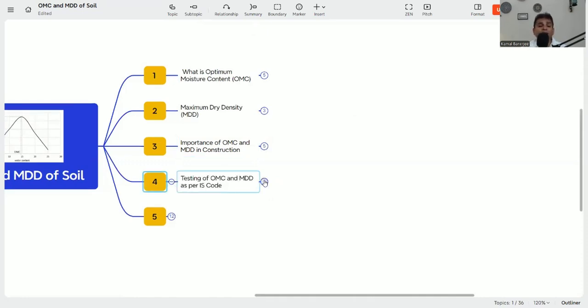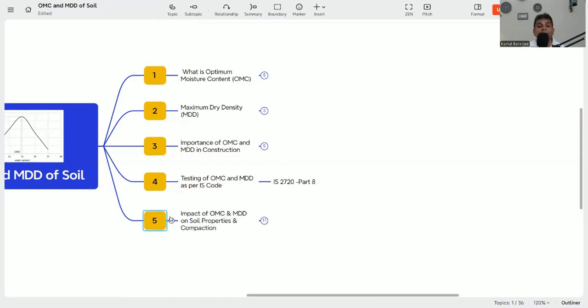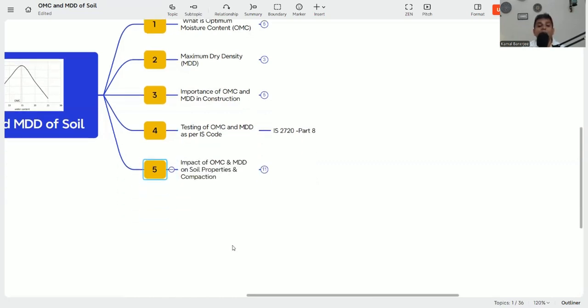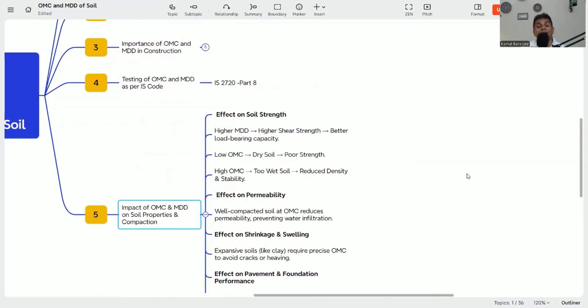And testing of OMC and MDD as per IS, that is IS 2720 Part 8, I already discussed. But how to do the test of OMC and MDD is a separate subject, and in another video I will discuss how you can perform OMC and MDD at site. The next part is the impact of OMC and MDD on soil property and compaction. Why? Because in soil engineering or geotechnical engineering, you need to know why you need to know the OMC and MDD.